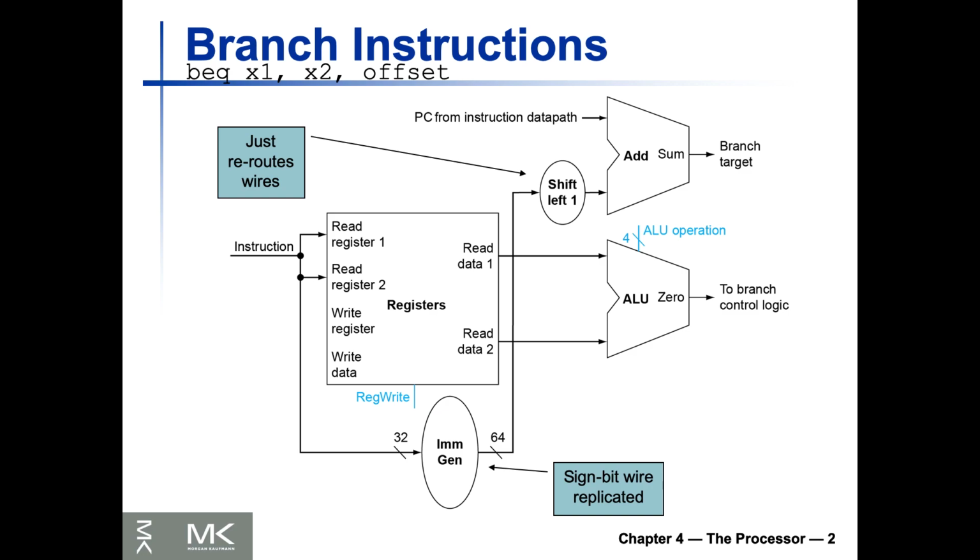So these were the first of the three. It is going to implement a branch function, BEQ x1, x2, and go to offset, right? We talked about it in a previous lecture. So first, we need to compute the branch target address, right? By adding the sign extended offset field of the instruction to the PC.